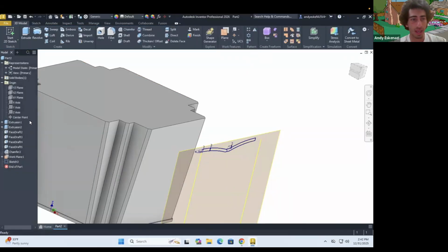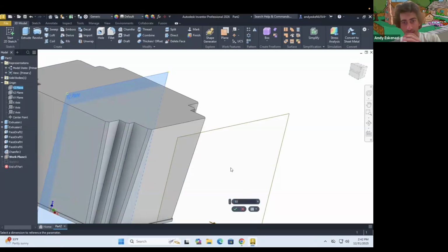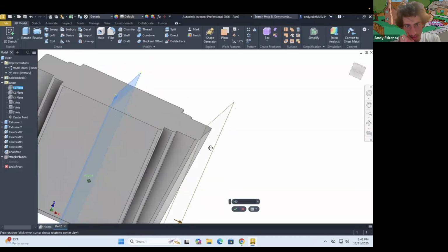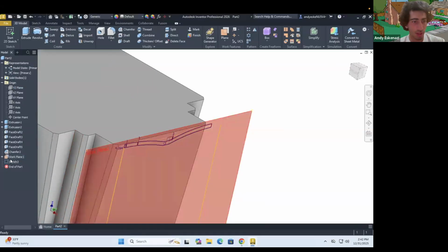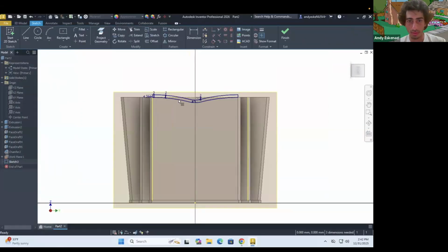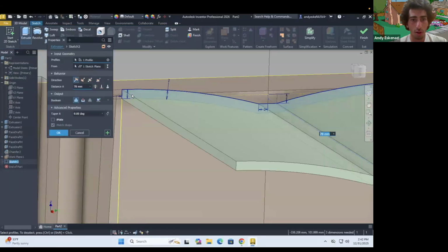Okay. I might change a little bit that plane in a second, but now I'm actually gonna save this and then I will go to that plane and say edit plane. Where are we? Edit dimension. We got 50. Let's see where that takes us now. Say 60. Well, 60 is fine. Good, that way it's right there. So then I'm gonna edit that sketch. Edit sketch. Boom. And 3D model, extrude.